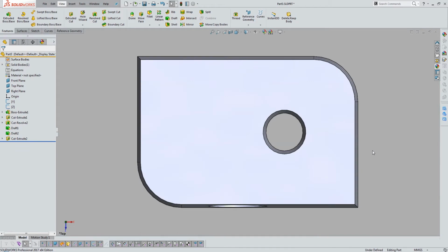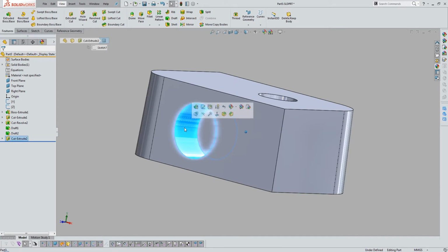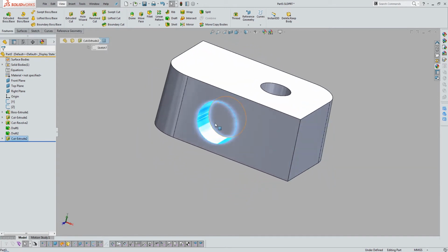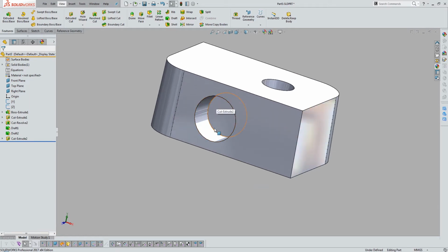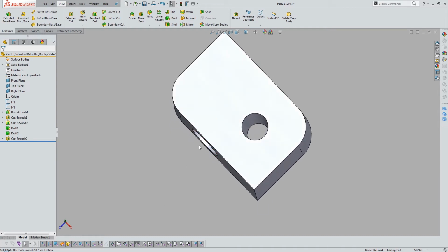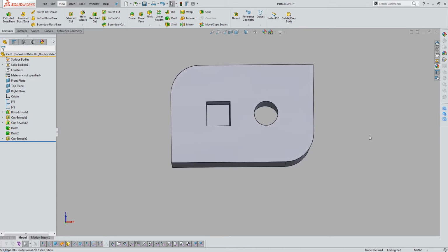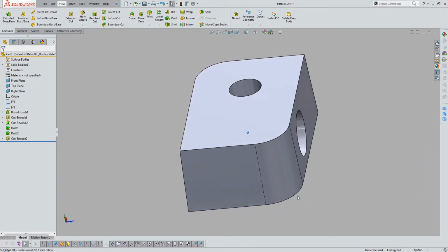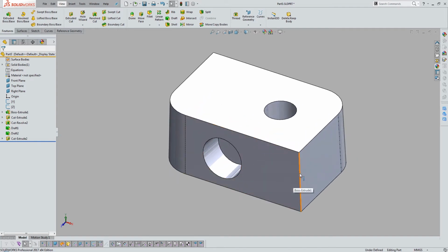with only two parts, a top part and a bottom part, I'll never be able to get that mold out of here. Any feature in our tooling, in our mold, that's going to create this indentation is going to have to be pulled out in this direction. And if I'm only pulling from the top and the bottom, that's not going to work. So yes, you can solve potentially difficult part drafting questions by adding more pull directions onto your tooling. That also adds cost and complexity to the manufacturing process.